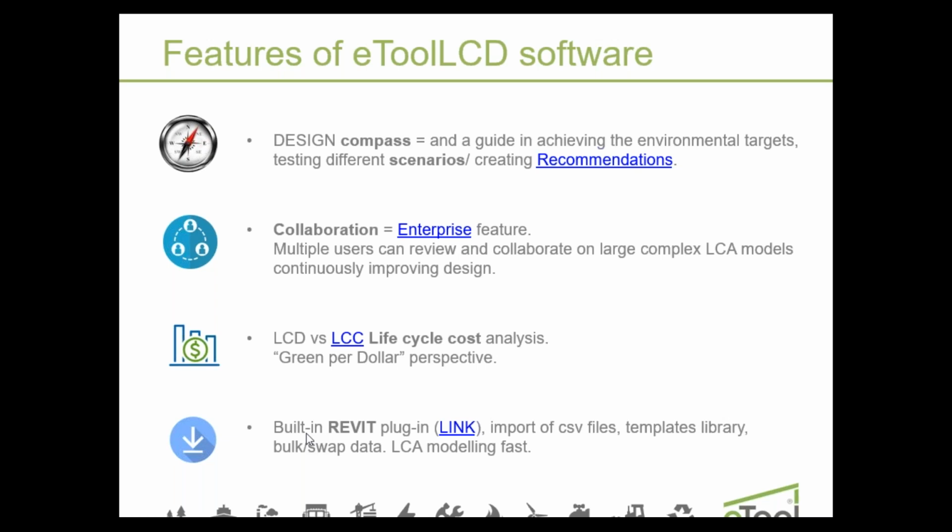Basically, it will mean that the software will translate a Revit model into the available templates and calculate the whole lifecycle assessment out of it. And there is a guessing mechanism trying to help the software recognize all these templates correctly. And once this is done, the matching is complete. Then the next time you change the Revit model and upload it back, the software will recognize all these changes and do the matching faster.